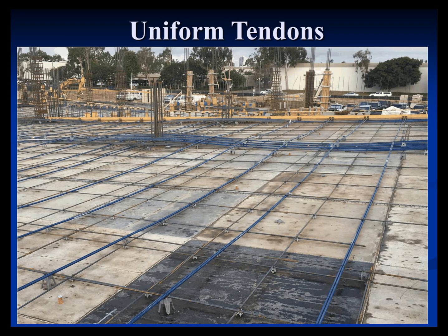But the one thing about doing observations, especially if you're new to post-tensioning, is everything in PT should be very gradual, whether it's the vertical movement of the PT, which is what we use for balance loads and to minimize stresses and control strength, or curving strands horizontally to avoid penetrations or to connect to a column or whatever reason. Everything should be done gradual. When I do observations, I take much more of a global approach.